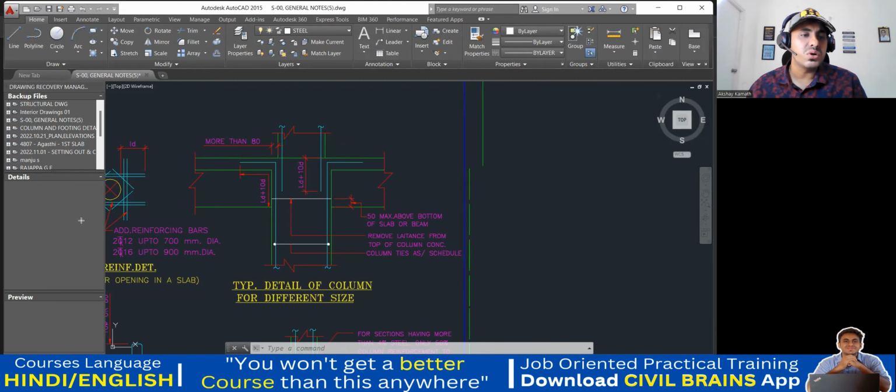So in that case, you can do one more thing. You'll bring a bar from here. If you don't want to continue this bar here, you can rest this bar: bring the bar, give a development length to that and stop it. You can insert this particular rebar inside the beam or inside the slab. Usually it will be inserted in the beam only, because anyhow that is a junction.